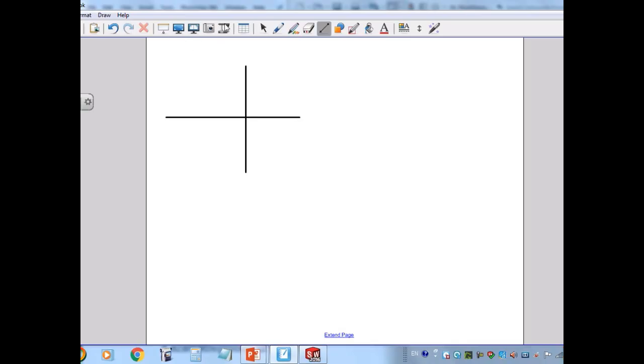If you see from the top, that will make a line like this in the top plane, and in the front plane that will make a trace like this, the vertical trace, and in a profile plane also makes a trace like this. Can you imagine that? So that is X, this is 0, that's Y, that's Z. So the plane looks something like this. So that's an axis.